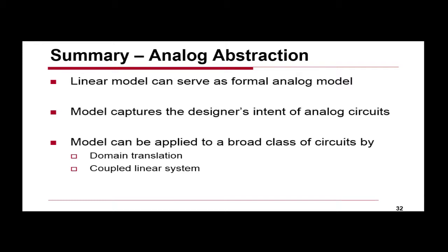And that's doing distortion correction in high-performance amplifiers, where you have to pre-distort the input to get a linear output out. I think it probably could be done, but that one, I'll grant you that maybe the nonlinearity in some time-dynamic fashion is important. But for everything else I've seen, it seems like it's pretty easy to fit this framework. So what we've done is we've said, OK, if we have this kind of approximation or abstraction, how could we leverage it to make analog design easier?